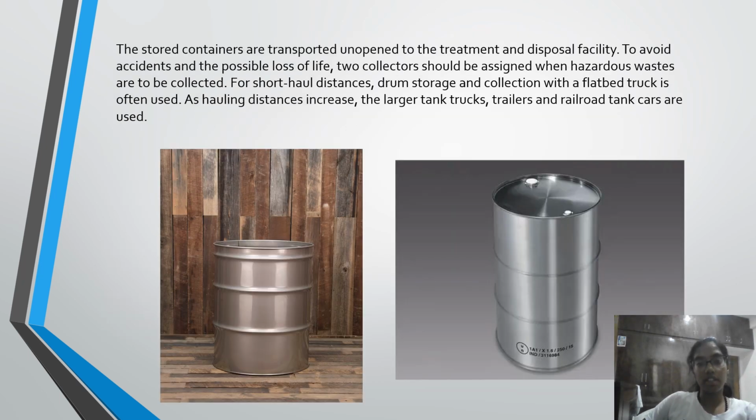So the stored containers are transported unopened to the treatment and disposal facilities. To avoid accidents and the possible loss of oil, two collectors should be assigned when hazardous waste is to be collected. So for short haul distances, drum storage and collection with a flatbed truck is often used.